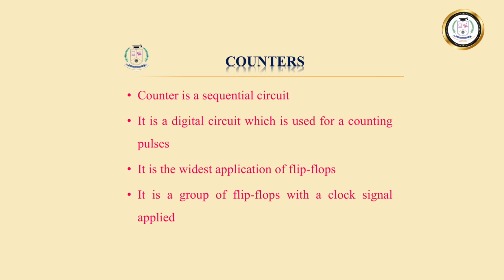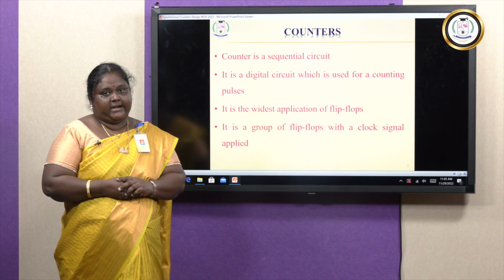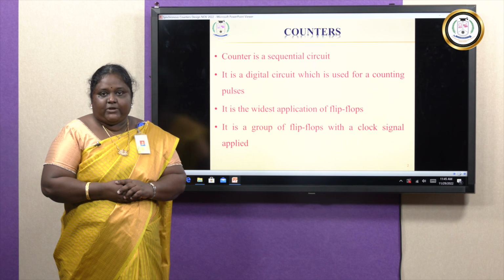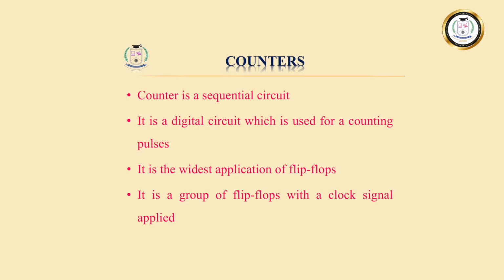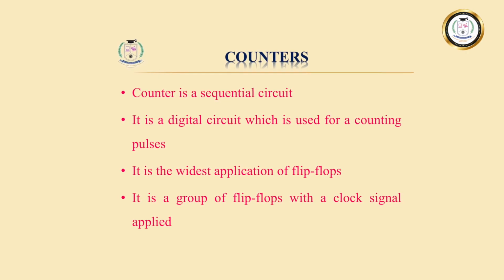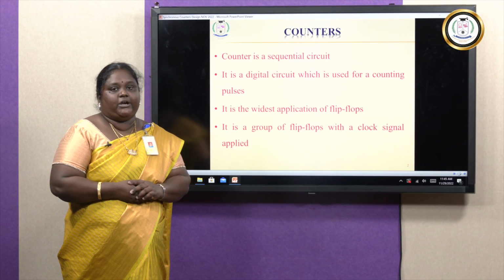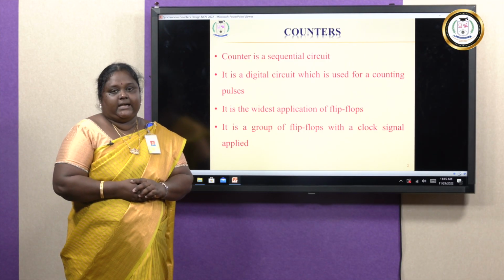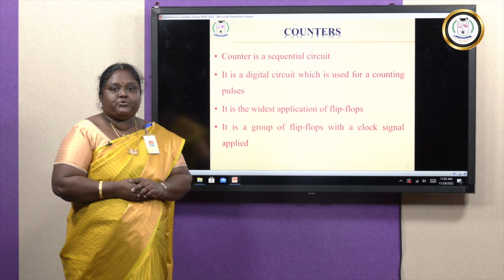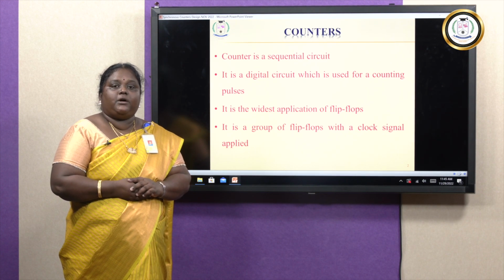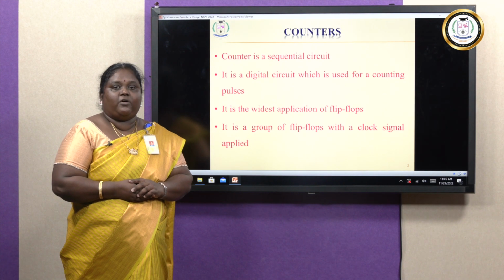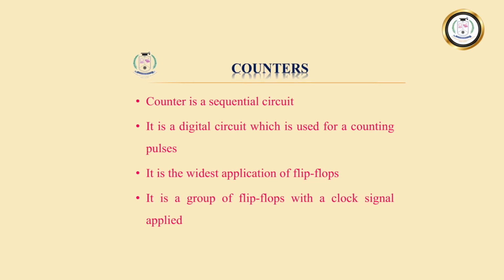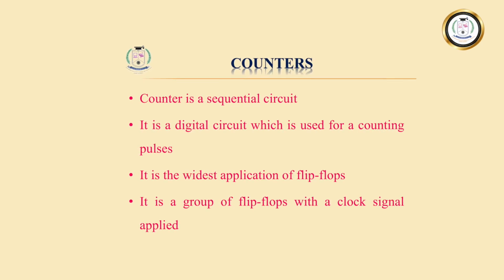Before getting into the design and implementation of a synchronous counter, let us try to understand what a counter is. A counter is a sequential circuit. In digital logic and computing, a counter is a device that is used to store or count the number of processes or events that have occurred, often counted with respect to a digital clock. Flip-flops are the basic building blocks of these counters.